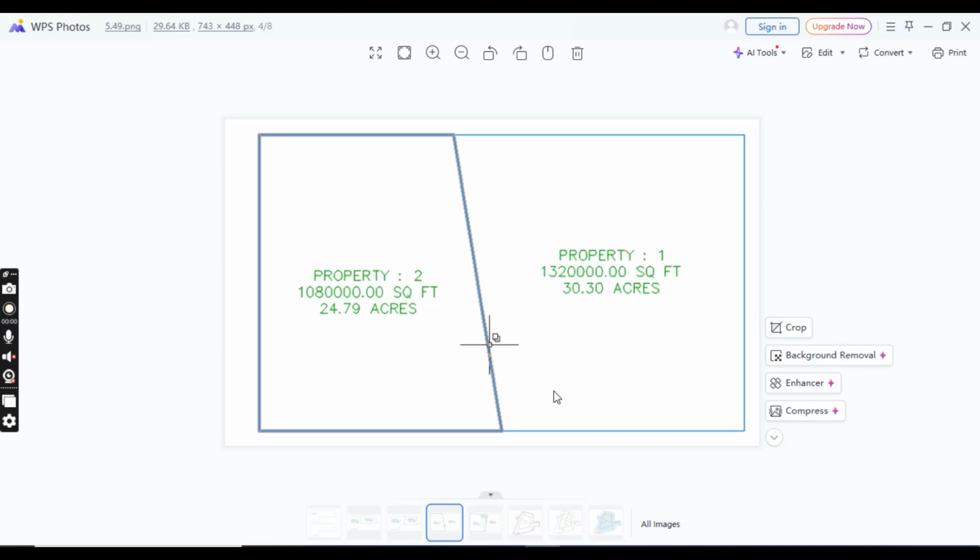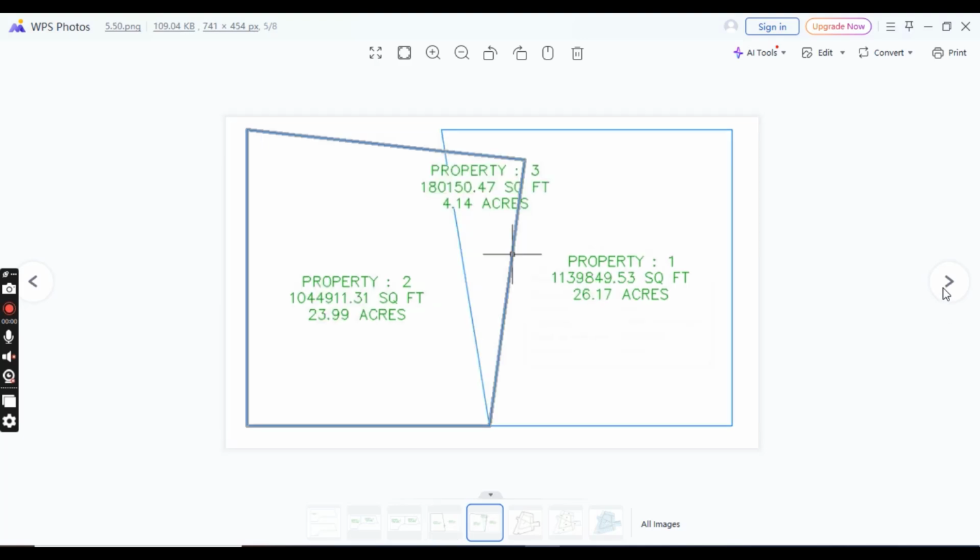You can notice that in this figure when selection cycling, Control plus W, is enabled. The duplicate segment becomes apparent when you attempt to edit the parcel segment. Moving one vertex from the common lot line, which you can see in this figure, reveals the second segment.